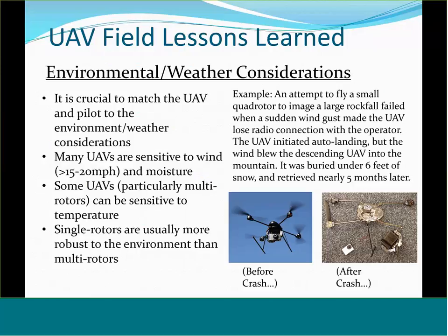Some UAVs, like we saw in Arizona, can also be sensitive to temperature. Others don't seem to be bothered by it. So it really behooves you to do your homework before you take a certain UAV platform out in a particular environment. One thing that we have noticed when you're in difficult environments where you might have temperature problems or extreme wind is that the single rotor platforms perform really well.